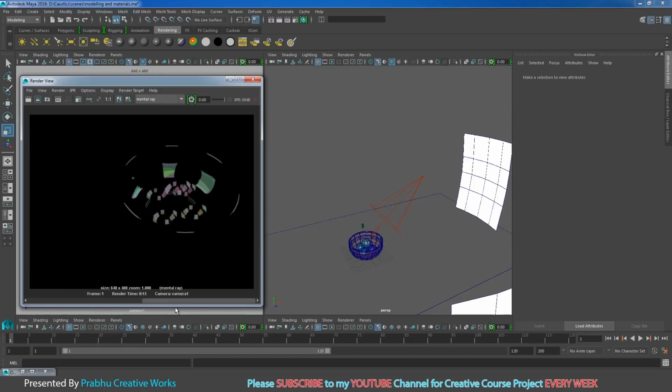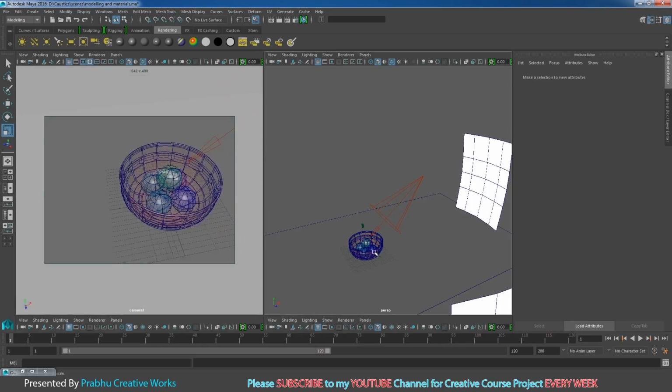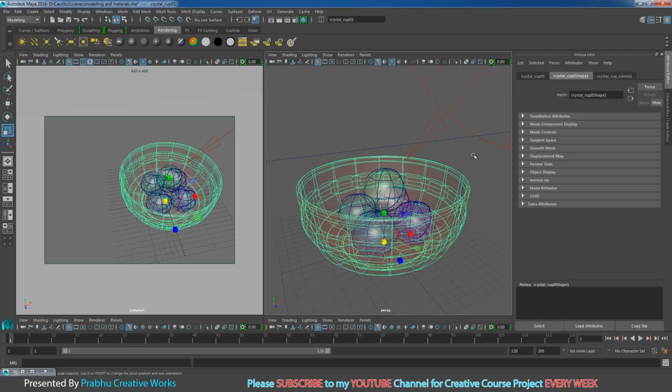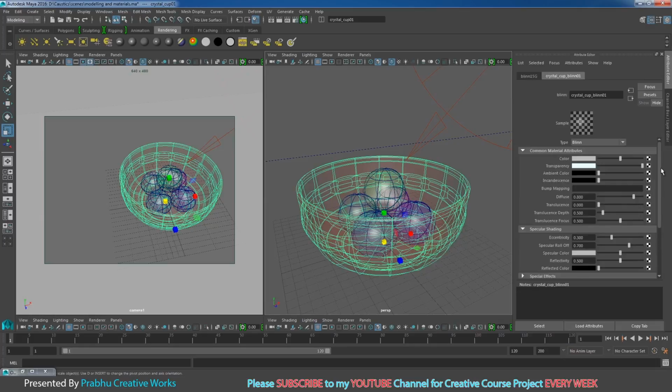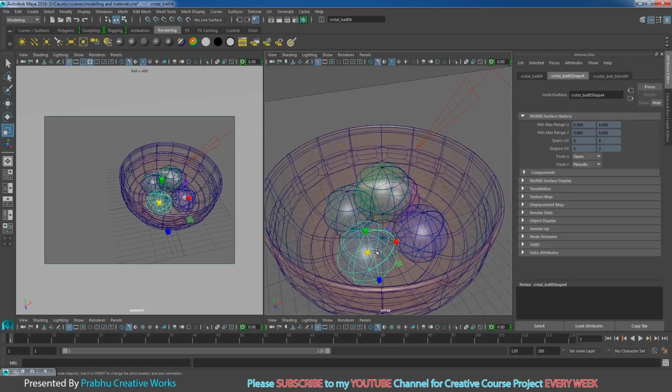See here, but our materials do not look very realistic. You want to turn on ray tracing for each and every material. I will select my crystal cup material, right click and choose material attributes. Go to the bottom side, here you have the ray trace option. I want to turn on refraction, so I will give 1.2. You want to do all the other crystal objects also.